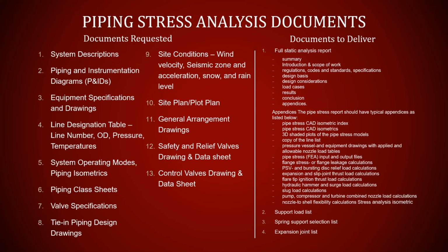If you have a pressure safety relief valve, you need to also include the calculation. If you will make the expansion and slip-on flange, you need to include it too. Flare tip ignition, hydraulic hammer and surge load, slug load, pump, compressor, and turbine combined nozzle loads, and nozzle shell flexibility, all of this, starting from PSV, is considered a dynamic analysis.